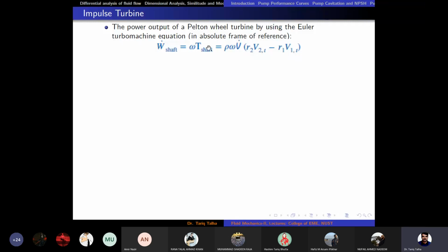Because the inlet angular momentum of the fluid would be larger than the outlet angular momentum, there would be useful work collected on the generator. But in the case of a pump, the angular momentum out of the fluid is greater than the angular momentum at the inlet of the fluid. That is totally opposite.